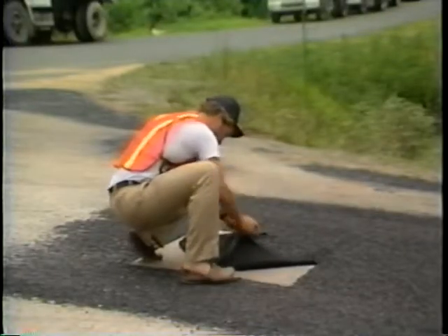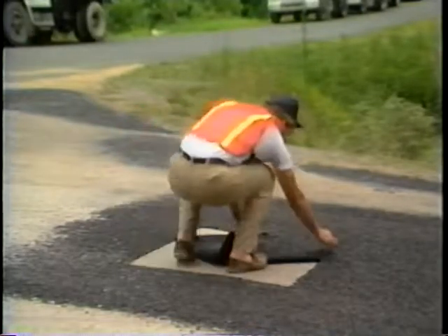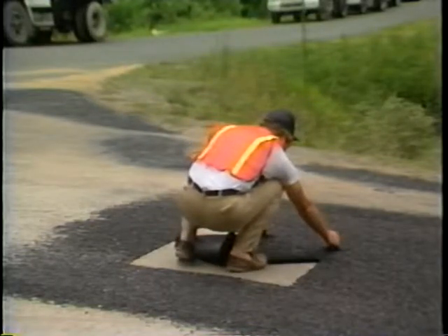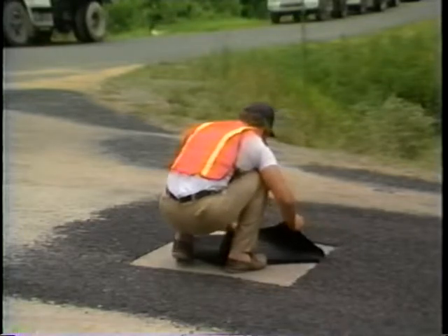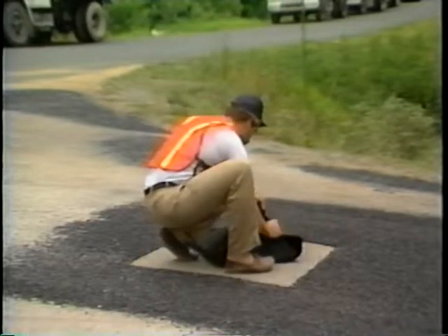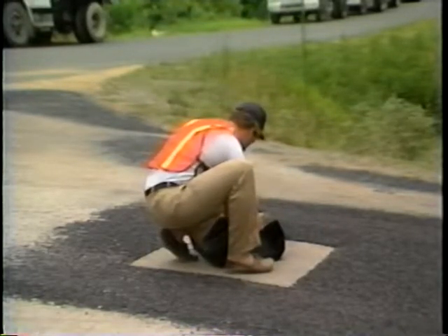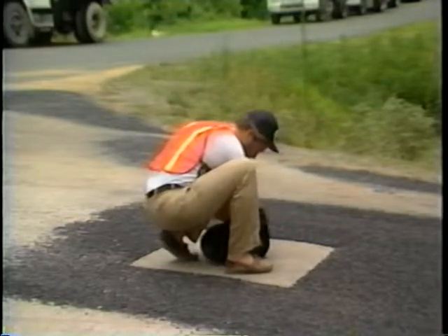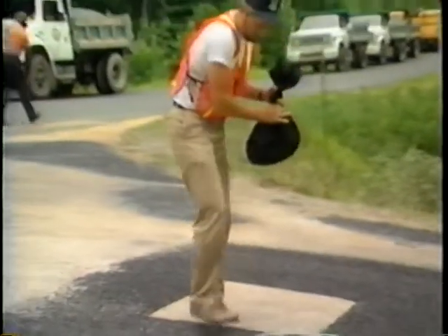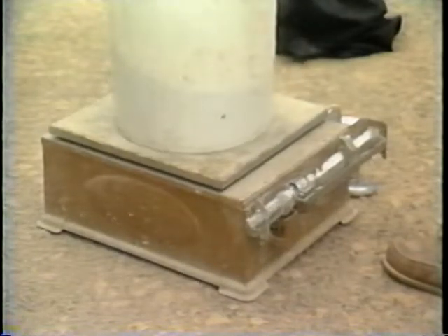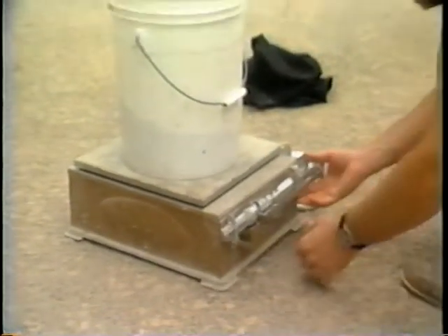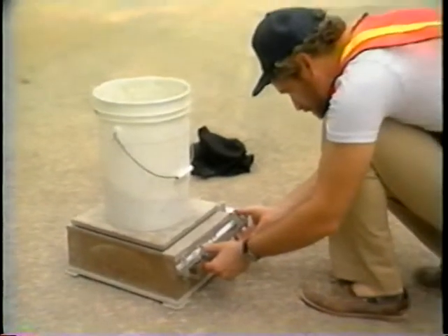Aggregate application rates, like asphalt application rates, can be calculated using a formula or taken from tables. Make a quick check on the amount of aggregate being applied by laying a 1 square yard section of cloth on the ground and passing over it with the spreader. Then carefully lift the cloth and the aggregate and weigh them. This will give the application rate of the aggregate being spread.